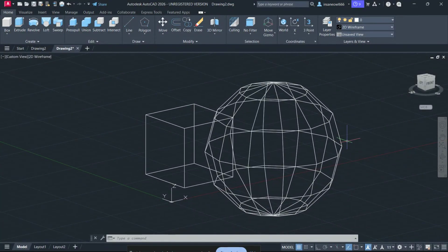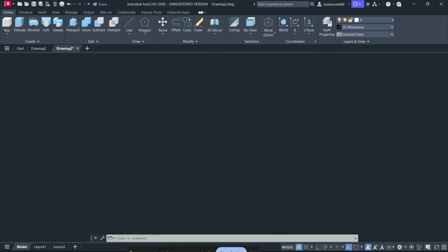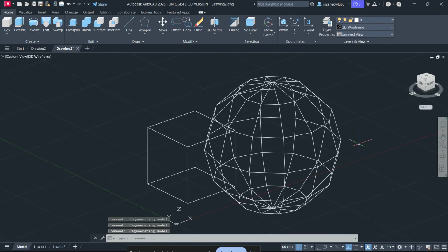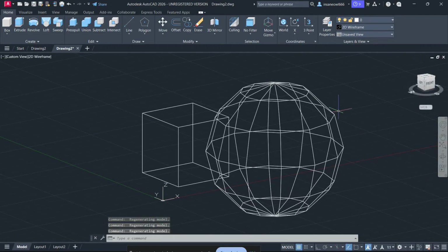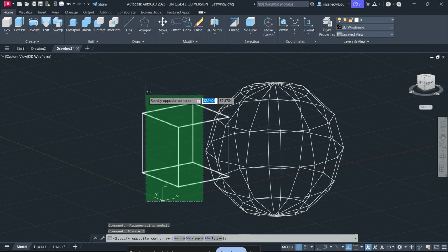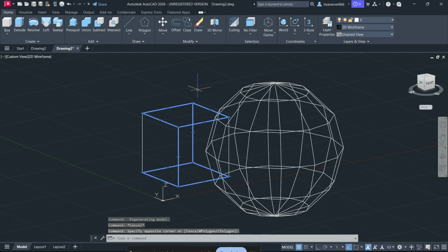If you're seeing AutoCAD error code 75015, this usually means AutoCAD is running into a modeling operation error during a fillet or chamfer. In simple terms, Autodesk ShapeManager cannot calculate a clean transition between two surfaces because the geometry is too tight, too complex, or too messy for the software to resolve. In this video, I'll show you what causes this error and the fastest ways to fix it.